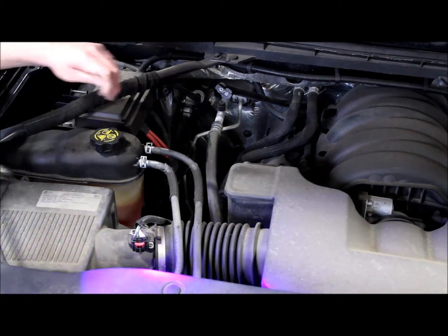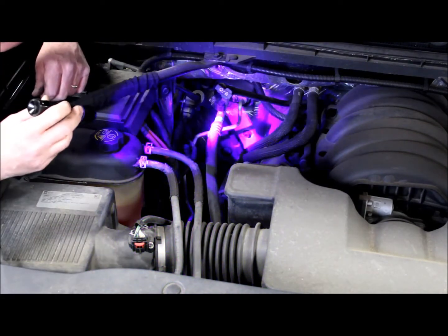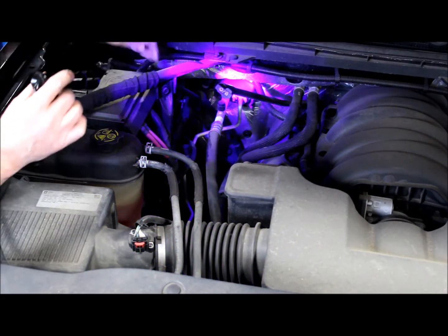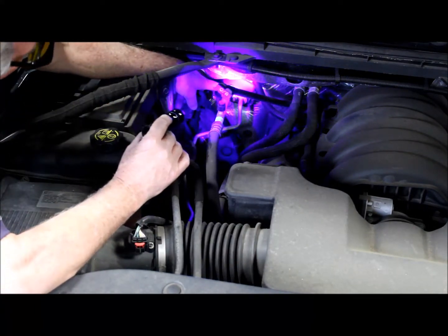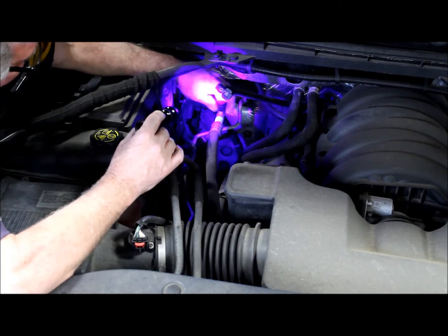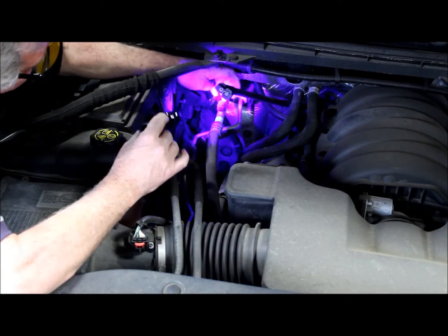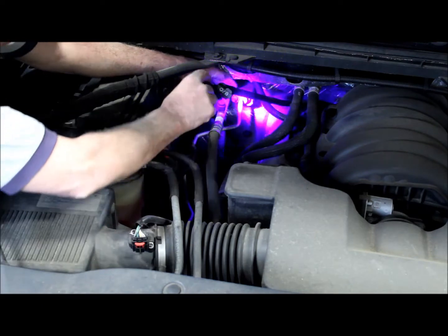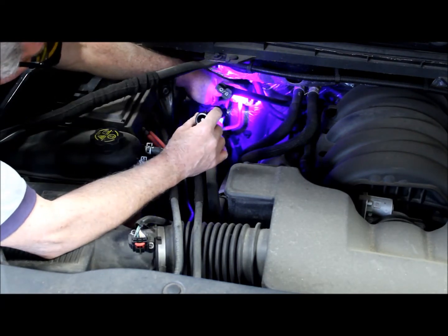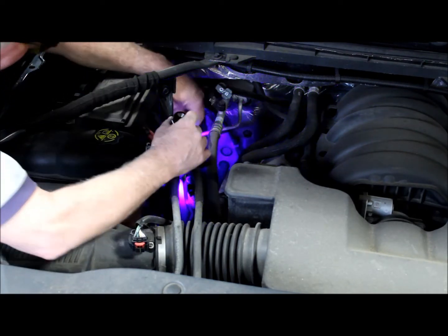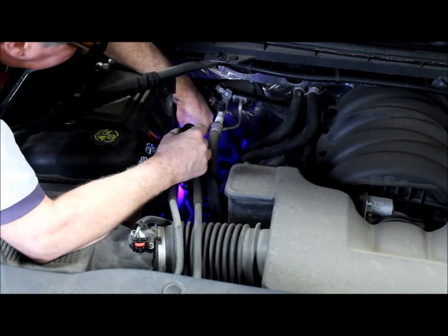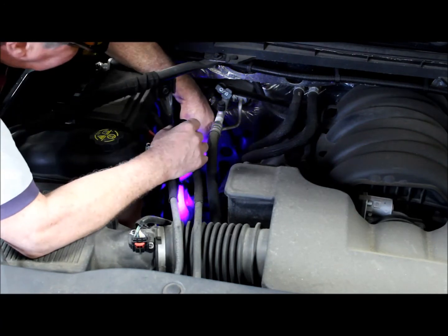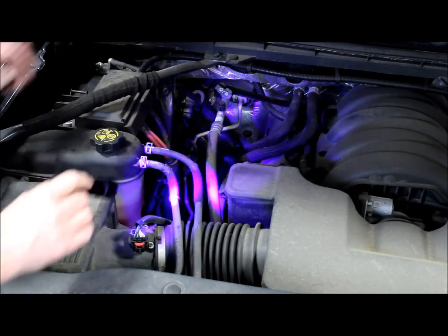Really no evidence of leakage there either. Again, now we have the vehicle on the ground, and we're going to check. Here's our thermostatic expansion valve. That goes through to the evaporator inside. Our low side service port, no evidence of leakage around there. Here's our high side line going into the expansion valve, and the high side service port. Now there may be a little evidence of leakage there.